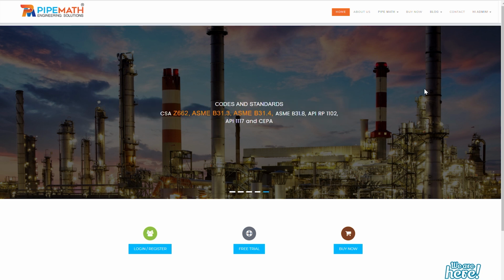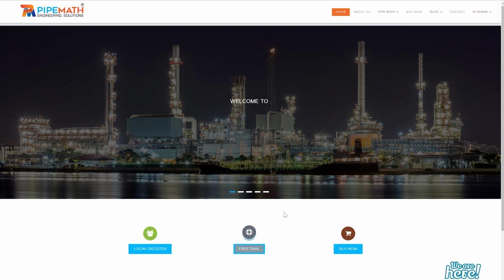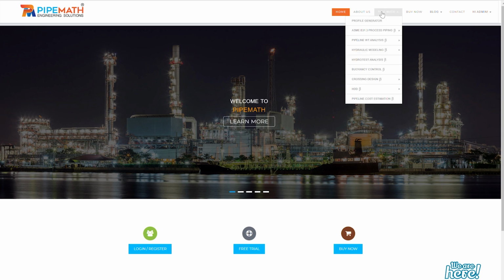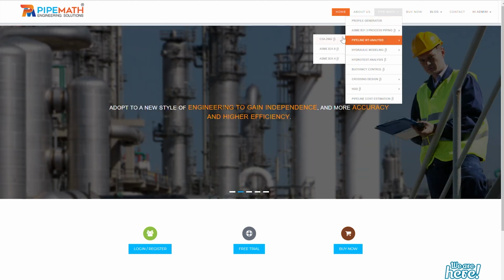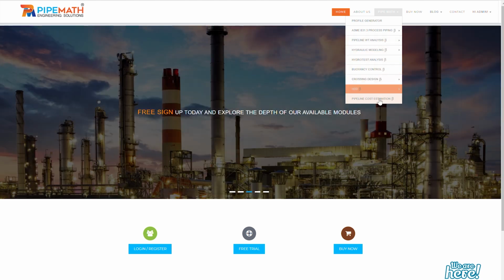We are going to talk about how to estimate the cost of pipeline projects, and for that purpose I just want to show you on Pipe Math. We are going to utilize three modules. The very first one is the profile generator. The second one is the wall thickness calculation, because the pipeline falls in Alberta, Canada, so we'll be using CSA Z662 for wall thickness calculations. And then finally, we'll be using the pipeline cost estimation module to estimate the project cost.